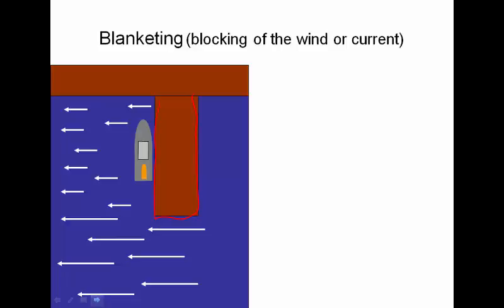As this vessel starts to back out of port, you can see it's backing up perfectly straight, rudder amidship. But as soon as the stern gets exposed to this current, with a pivot point right there, and we're operating in stern propulsion, so our ship's pivot point is right here, this is where the current is acting. It's going to create a moment that's going to move our ship in this direction.